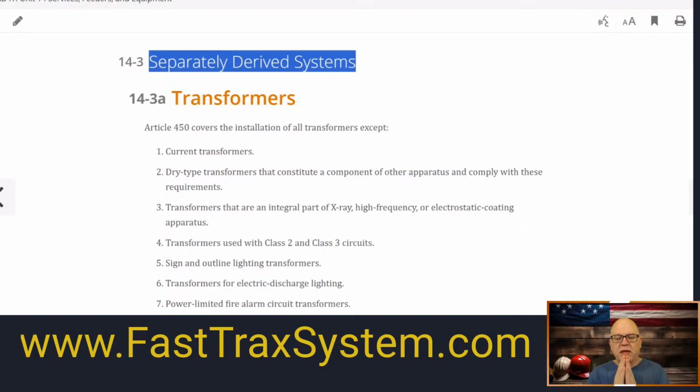And so in that separation, we have electromagnetic induction that transfers power from a primary to a secondary. Now, as far as the grounding, the grounding is intimate with the primary to secondary, okay? Because you have to bond all this stuff together. They come together on a common terminal block, okay? And so in that scenario, you want to make sure that you got your primary and your secondary. Again, if they were to touch, then it would fault out. So that's all built in the transformer.